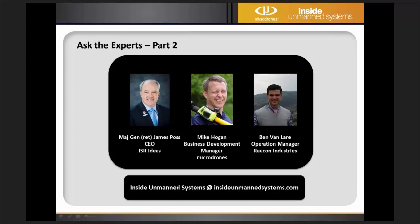As a matter of fact, and we can possibly talk about it at another webinar, one of the concepts we're talking about is coming up with a bubble of airspace that's going to be managed by unmanned traffic management systems, and inside that bubble it'll be covered by ground-based sense and avoid radar and this data link that we've got to develop in a new computerized system for managing the air traffic. And one of the things the FAA is thinking about is, do we keep manned aircraft out of that bubble? If we allow manned aircraft in, do they have to have similar equipment to what the drones have? As an absolute minimum, you've got to have ADS-B. You probably don't need 360 automatic detect and avoid like the drones may have to have, but it's a valid question.